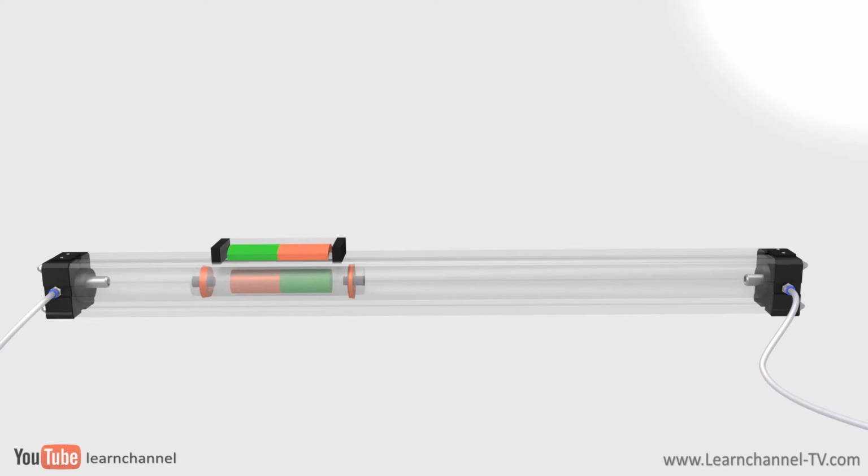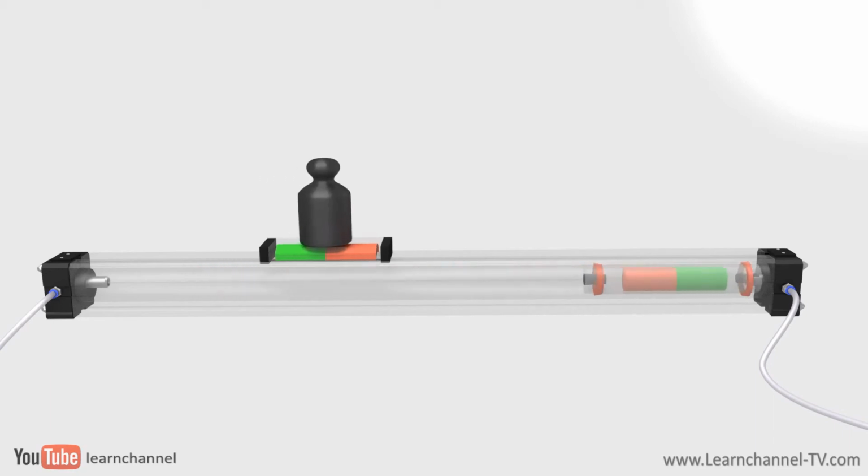You get a leak-free cylinder with less wear compared to the other types of rodless cylinders and no ingress of contaminants. However, the magnetic coupling is also a force limiter. If the load is too high, you have to worry about decoupling.